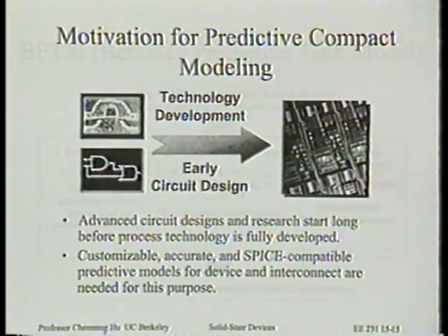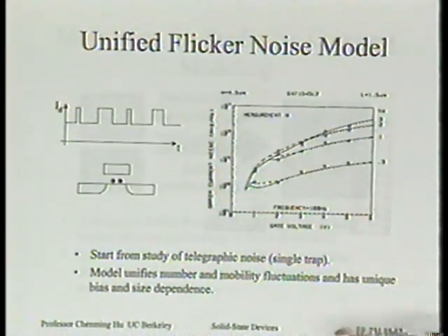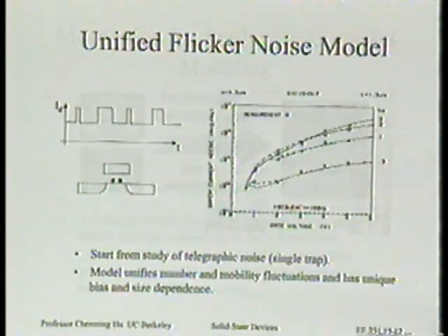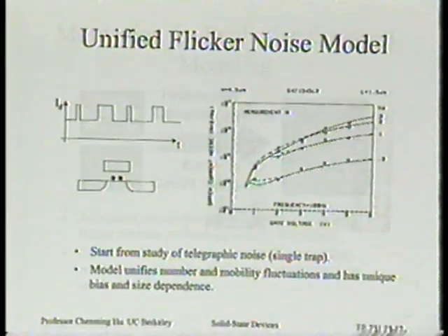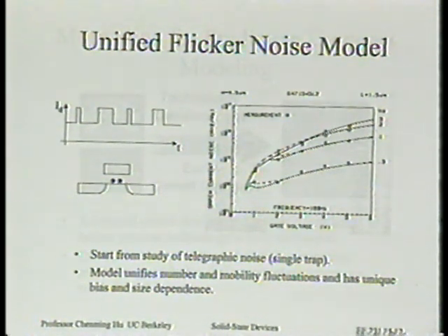So that's the end of the review of the compact model, with some emphasis on the noise, because we haven't really talked about thermal noise, and some emphasis on the intrinsic input resistance, and a little bit about the substrate network. Turns out those are what's important to understand and determine the behavior of the transistor. And just by adding those resistances, the transistor model, as we understand it, does agree with data all the way very close to FT, tens of gigahertz. Okay.